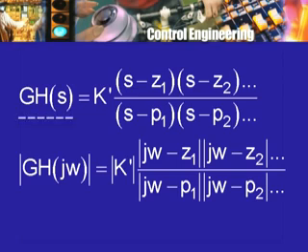All right. So it will be useful to have some other and a little better way of finding out the frequency response, and this is exactly what Bode did. So for that, let us write down the transfer function GH of S as some coefficient, I will call it say k prime, which is positive, multiplied by (S minus Z1) into (S minus Z2) and so on, divided by (S minus P1) into (S minus P2) and so on. Where there are zeros, Z1, Z2, etc., there are poles P1, P2, etc., this coefficient is just some real number.